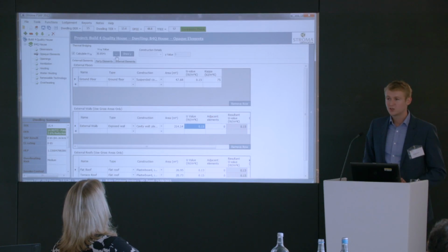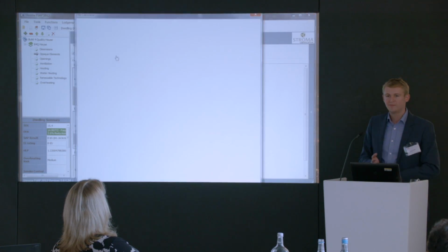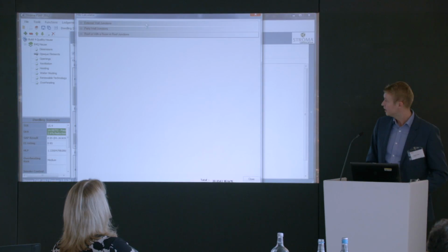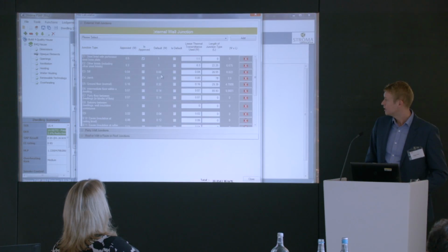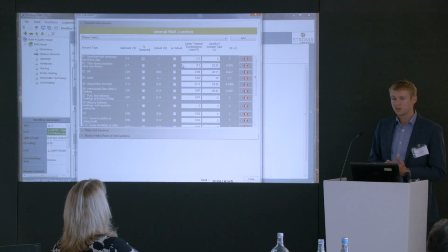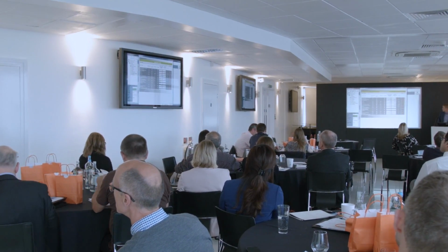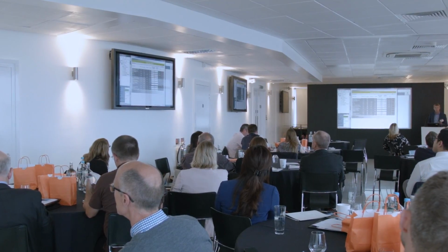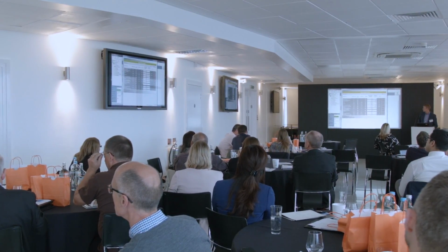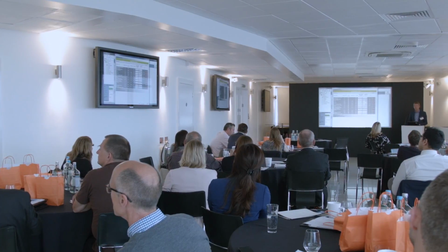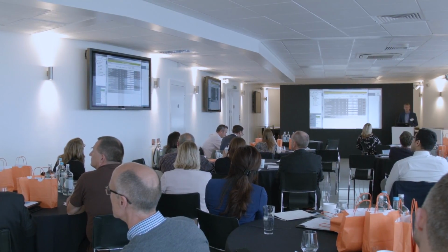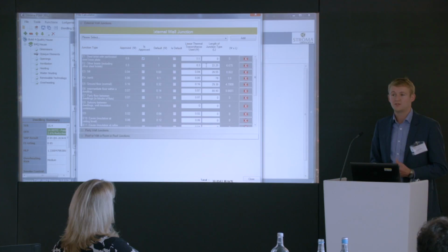Quick nod to thermal bridging. I talked about it earlier. I said it's one of my favourite topics, which is probably quite boring, but ultimately what we have in SAP is a list of all the available junctions that we have in a property and what the psi value is for those junctions. So you can see in this property we've got a total length of all the lintels. They're coming in at 22.25 metres. They are all given a psi value, in this case of 0.3, and that psi value has been lifted from the accredited construction details. So that, in effect, is an industry good practice detail.